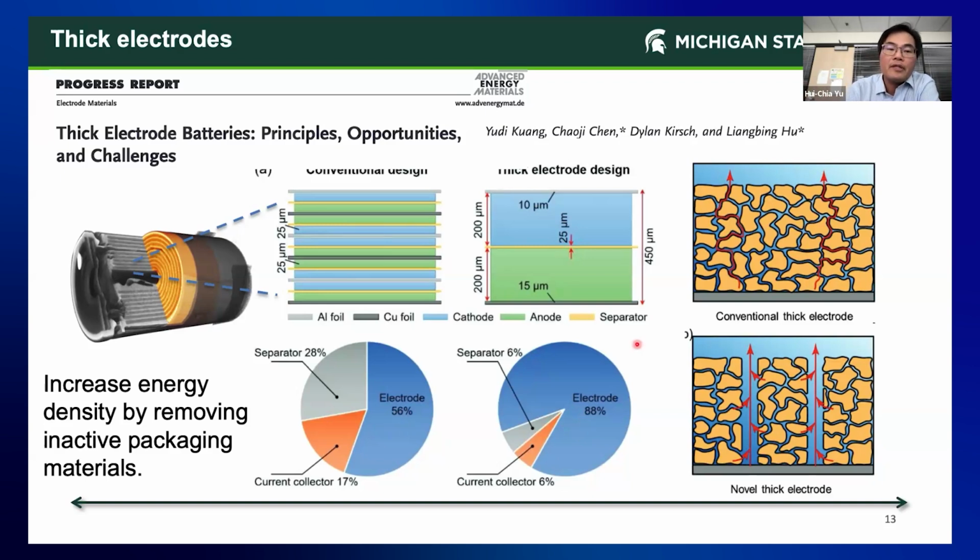But you can imagine, right, if you have a very thick electrode, diffusion, the tortuosity channel becomes a limitation for your lithium ion diffusion. So this engineering idea is called perforation. You are digging tunnels through the thick electrode, so that these tunnels serve as a highway to carry fast lithium transport. And in the original electrode, you have this local road, right? The lithium has to travel slowly through the original region. So that's the overall idea.